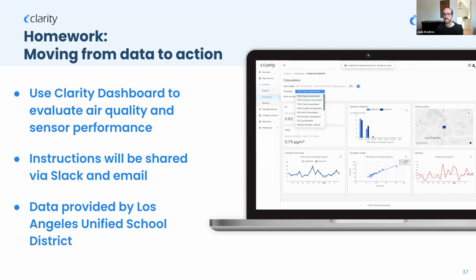Some sensors, like gas sensors such as NO2, will actually perform much better at higher ranges. If you have conditions of 50 to 100 ppb of NO2, you'll likely have an even better performing NO2 sensor, because you will have a high signal-to-noise range. So I think ambient air quality in highly polluted areas is a great use of low-cost sensors. The only thing to keep in mind is to make sure calibration and evaluation are under similar conditions so we can continue to monitor them.